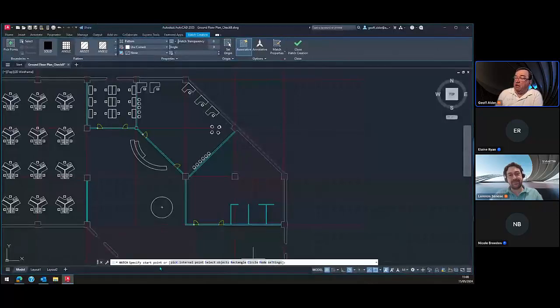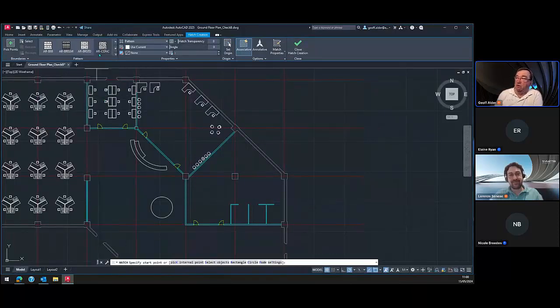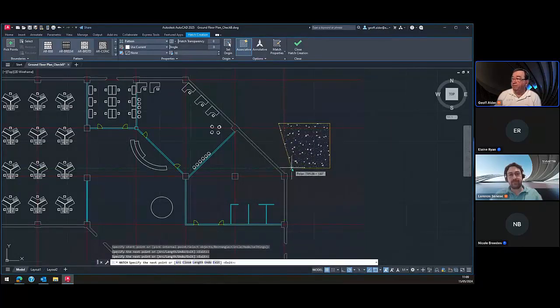So modes, the normal pick internal point and stuff is available here. So if I choose like a concrete there, for example, and then I make my scale a little bit bigger here, jump into a mode setting here, I could use an area setting. So I can click on an area and then basically describe an area like this.